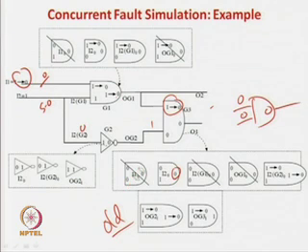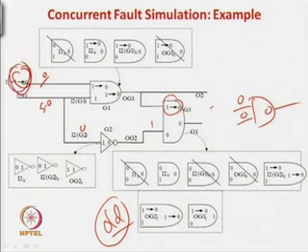So in fact what we are doing over here is, just by this change from 1 to 0, this is the old list which was available with us. So we are just finding out what the changes are by this change, what are the changes in these gates, that is the bubble list. If something becomes equal to 0 0 0, we are deleting it, and if something is not becoming equivalent, we just retain it. So for I2 0, there is a signal difference between this one and this one, so this gate is retained.